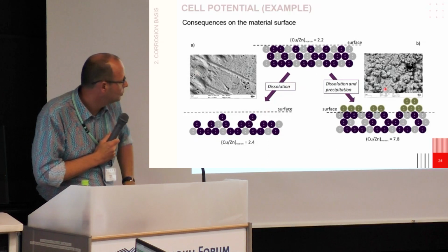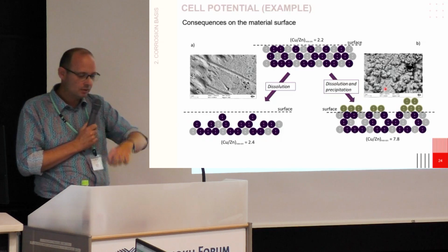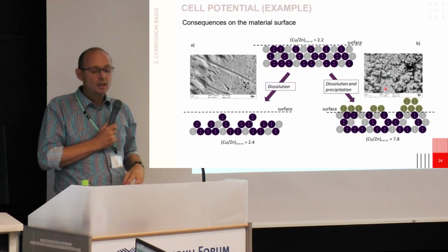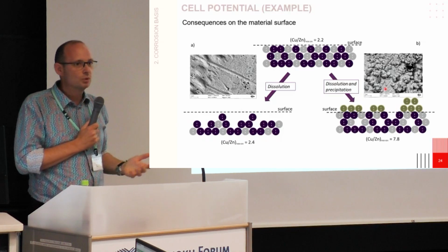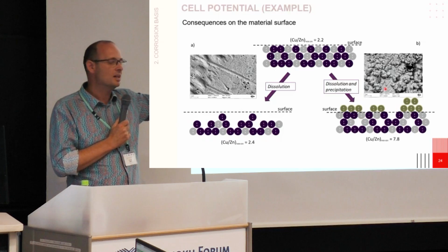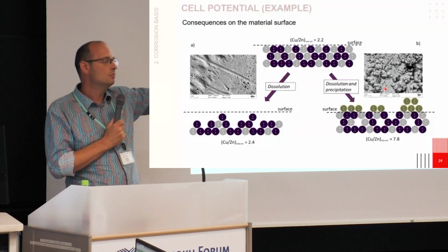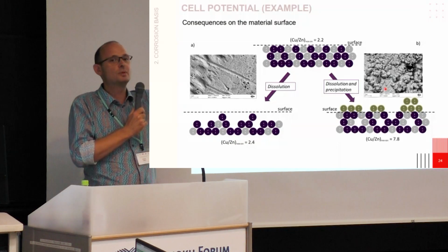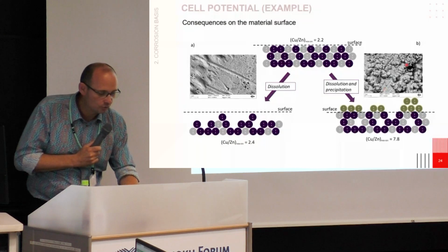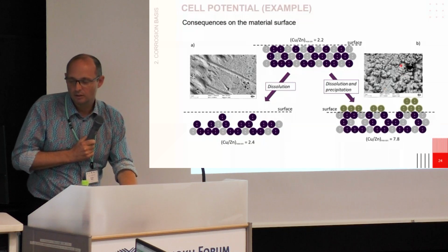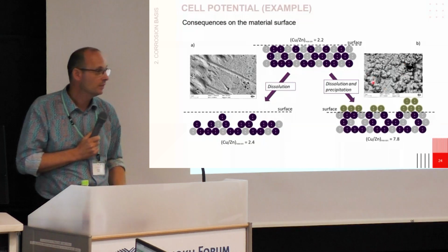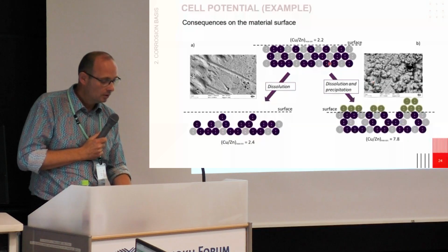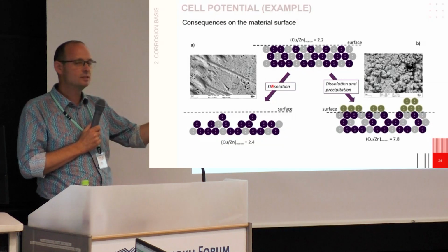And if you look at the surface, you will say, yeah, but there are a lot of grains and crystals appearing. Yes, actually, there is a second process. If you remove zinc in a brass, copper atoms are no longer attached to the lattice, so they tend to rearrange, and you can have such beautiful crystals. At the opposite, if we are in nitric acid environment, we said that both elements will dissolve.